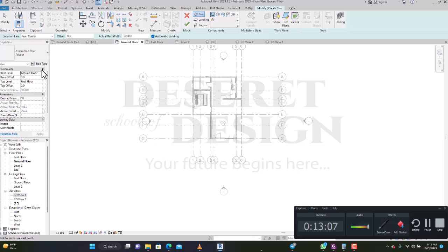Now we also have a base offset. I don't know whether you know what the base offset is. Do you know what the base offset is? Okay. We've been doing that with walls, but you've forgotten. Now, base offset means that even though you are connecting the wall to that level, you want it to go at an offset value. Do you get it? So wherever this level goes, it will maintain that offset value. So let's say this is my wall. Now this is the level.